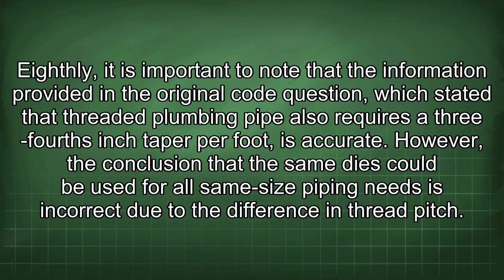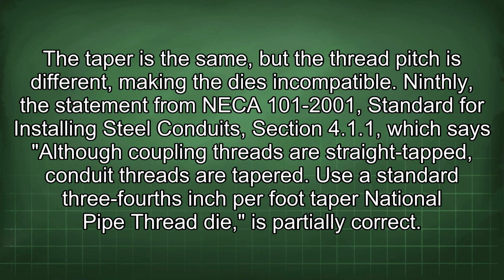However, the conclusion that the same dies could be used for all same size piping needs is incorrect due to the difference in thread pitch. The taper is the same, but the thread pitch is different, making the dies incompatible.